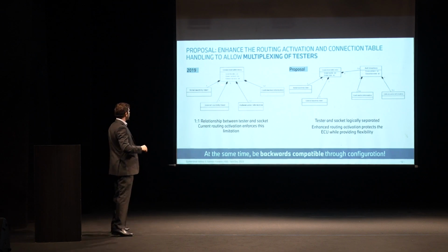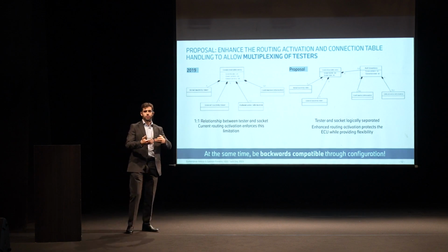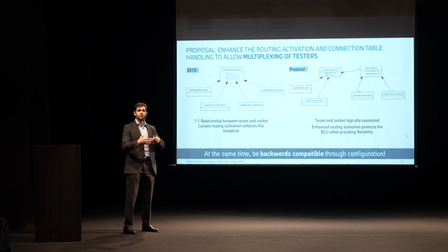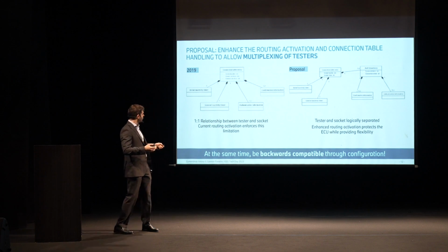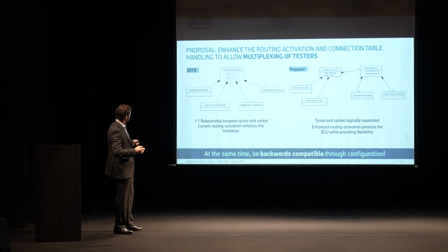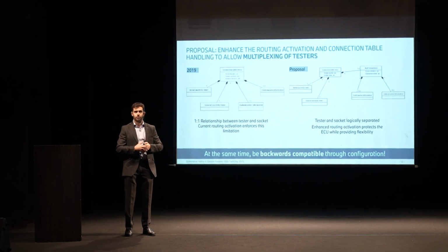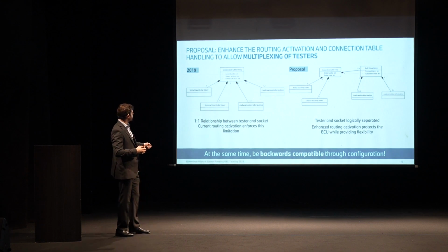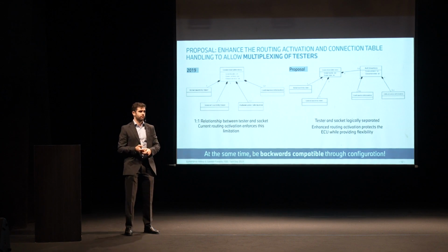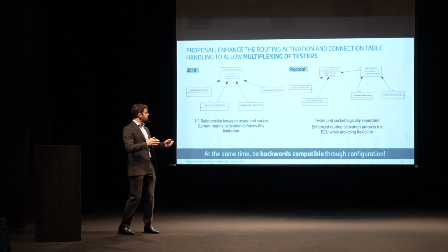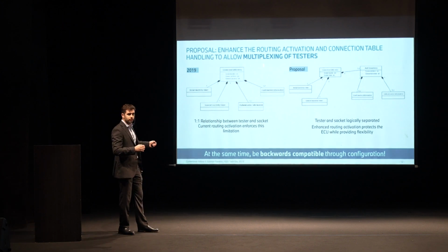So in the current modeling of the ISO, we have a so-called socket handle in that modeling object, source address, and a so-called connection state, which is registering the socket status and the DoIP connection status. Then we also have so-called initial and general inactivity timers, which are mechanisms to handle the sockets from the disconnection point of view. And then we have some optional information related to the tester, which is called the authentication and confirmation information.